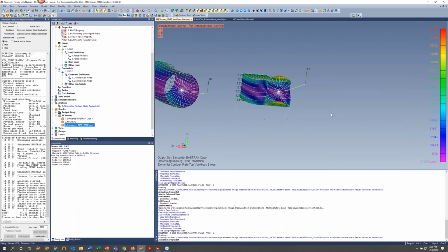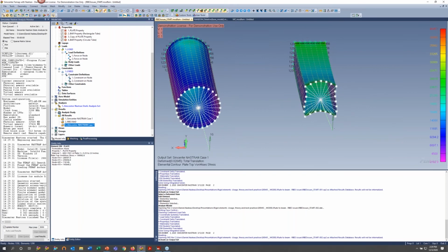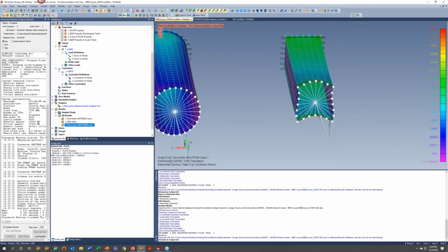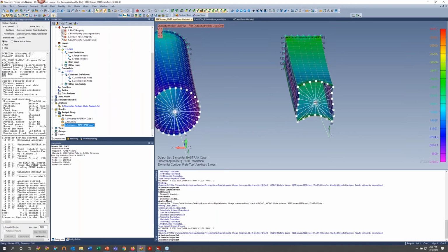The reason why I did this as a circle and a square is that you'll notice that the load is being transferred a little bit different between here's the RBE3 picture and here's the RBE2 picture, because this is infinitely rigid, and remember it's going to stay the same shape. Where this one, it's a weighted average based on the length of the legs, and it's a little bit longer to get to the corner than it is to get to the side of the square here.